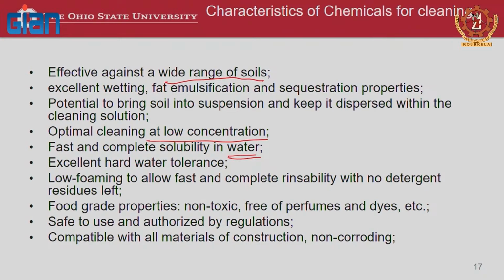And a lot of the time in the plant environment, you may have hard water. Hard water means how many minerals and other things you may have in your water. Sometimes you have the luxury of getting very pure water, but in a cleaning plant environment you may not have that luxury. So, you need to see whether you are able to work with a wide range of water, and it should have a low foaming capacity, so that you are able to rinse without any detergent residue. When you have foams, the foam settles down, and it may leave some detergent residues. So, you want to get rid of them.